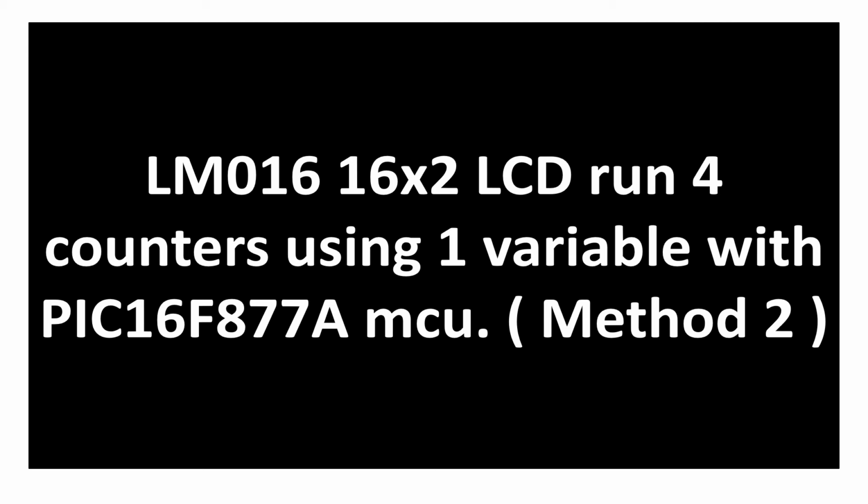In this video I will show you another technique, how you can run 4 counters on a 16x2 LCD using a single variable. So this will be the second method. In the previous video, I used the LCD out command. In this method we will use the cursor to move the data here and there.